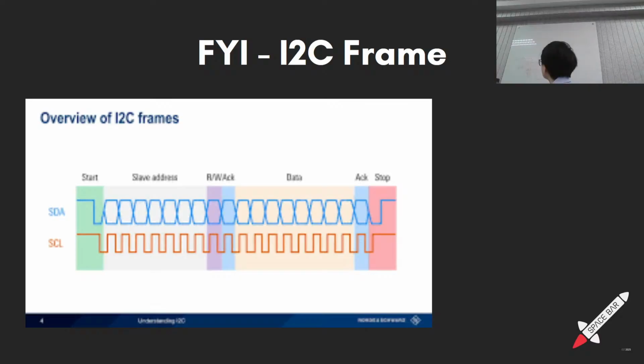Doesn't the pull-up resistor just flood all of the wires with like 3.3 volts? Yeah, that's the whole point. But then how do you send the signal at all if it's flooded? Because this is just a resistor. So let's say this is 10K ohms, a relatively big value. When the transistor is turned on, it's more like 30 milliohms. Basically zero. It's so small that nobody cares.